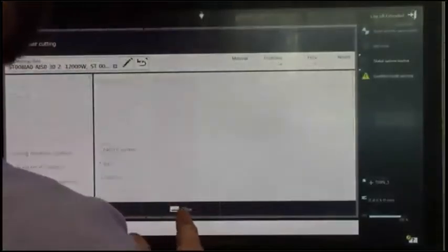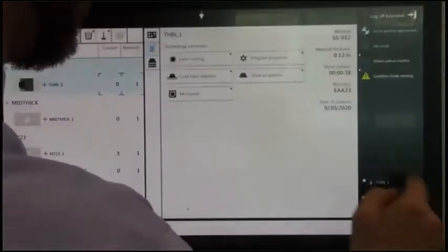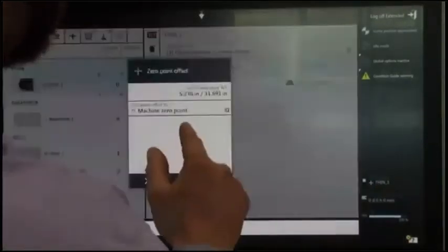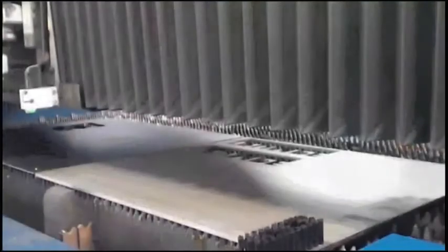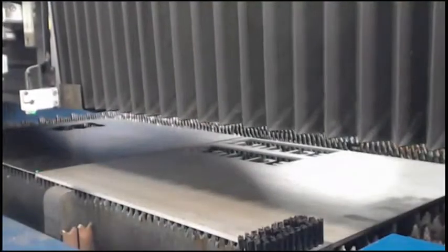Again, super easy and quick to change this. So we're going a little slower here, 1,840 inches a minute for our air cutting. And let it go. I actually think that this uses the same nozzle, so I don't think it's going to change. Oh, nope, I lied. It is changing.